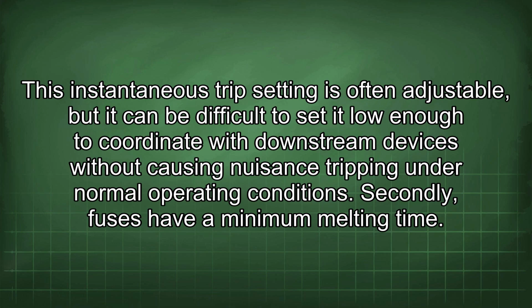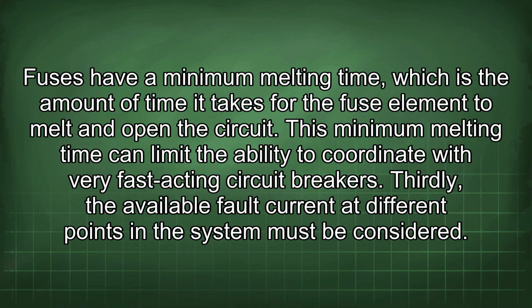Secondly, fuses have a minimum melting time. Fuses have a minimum melting time, which is the amount of time it takes for the fuse element to melt and open the circuit. This minimum melting time can limit the ability to coordinate with very fast-acting circuit breakers.